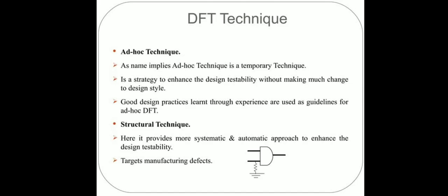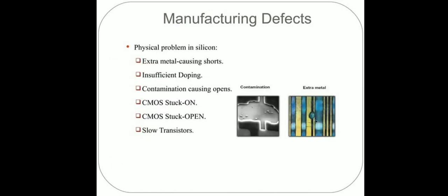In the case of DFT, there are two techniques: one is the ad hoc technique and the other is the structural technique. As the name implies, ad hoc is a temporary technique that we use for enhancing the design testability without any change in the design style. Good design practices are used as the guidelines for ad hoc DFT. In the structural technique, we provide a more systematic and automatic approach to enhance the design testability.